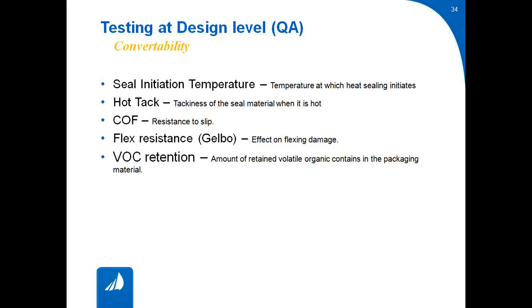So there are certain factors which you need to test to ensure that my product design is perfect after it is a laminate. What is that? Seal initiation temperature. At what temperature does the sealing happen? If the end user doesn't know, he may seal it at a higher or lower temperature and there may be failures. And if the product is very sensitive to heat, we need to give some sealant which seals at a lower temperature. Of course, it will go to a higher cost, but that's possible. That is seal initiation temperature. I will explain how we declare that.